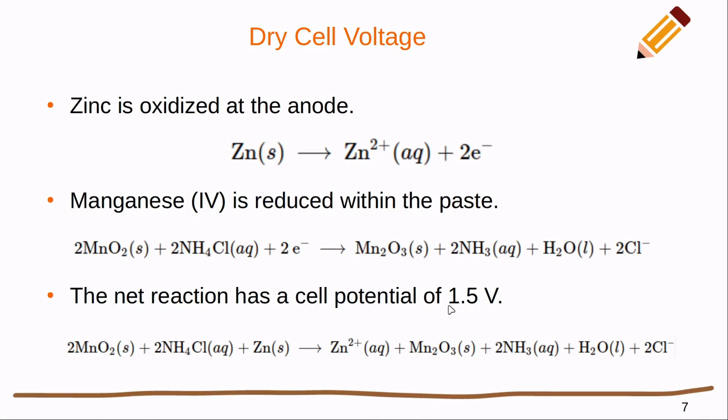And we've actually worked, because we started off with these dry cells, to produce batteries that work at this 1.5 volts or some multiple thereof, which is where we come up with the idea of having 3-volt devices or 6-volt devices, or even more commonly 9-volt devices or 12-volt devices. They're all multiples of this 1.5 volts, and that's where that initially came from, and we just kind of stuck with that.